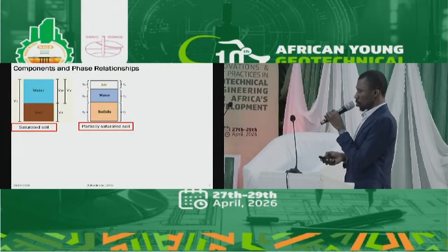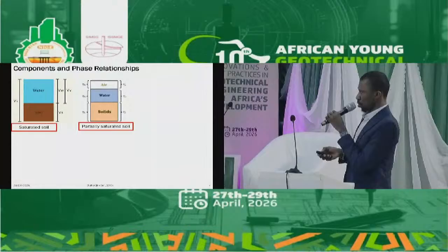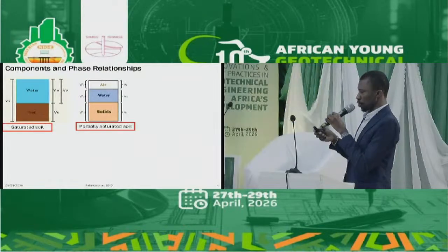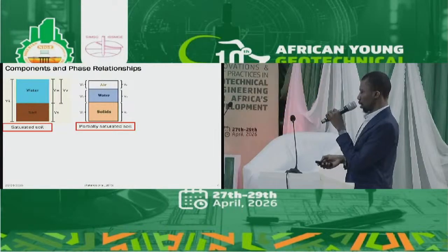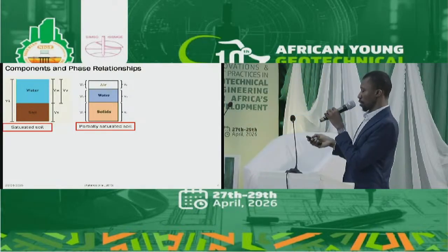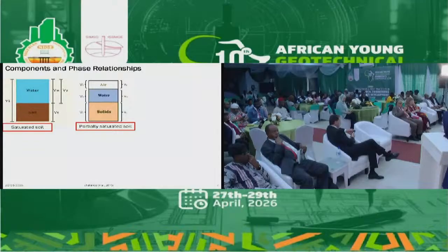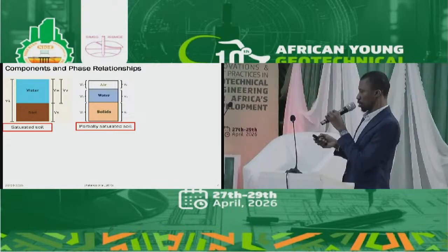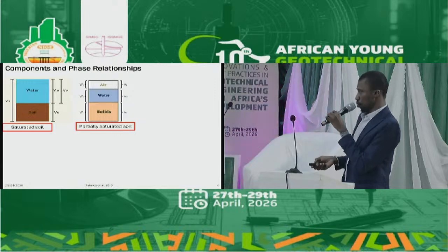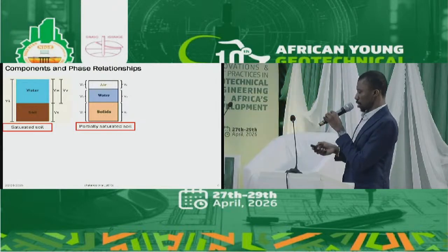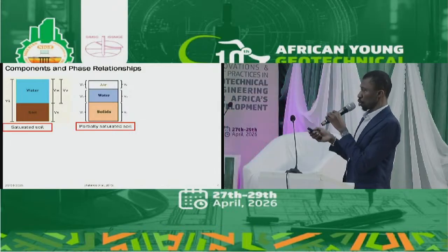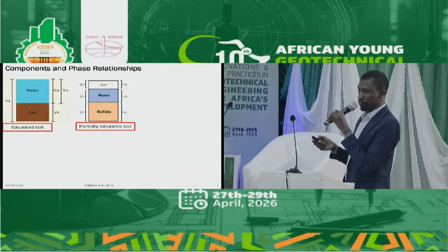When air is present within the soil with water, we have an interface between the two. The air-water interface, also called the contractile skin, acts like an elastic membrane which influences the mechanical behavior of the soil, thereby putting more strength into the soil. This effect of partial saturation is common in tropical residual soil, collapsible soil, and compacted fine-grained soils.